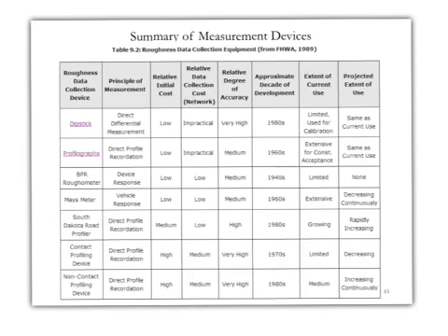And the relative initial cost is typically lowest with dipsticks. For profilographs, and once we get to, for example, the South Dakota profilometer, it's kind of medium, and then once you have profiling devices that use accelerometers and lasers, the cost is going to be pretty high.